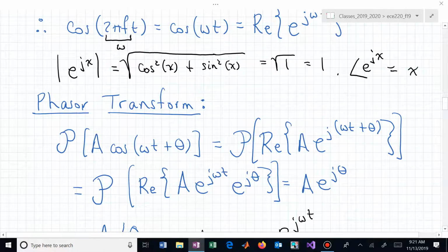All of that to help us get into the frequency domain to do phasor analysis. We want to now, instead of having to deal with sines and cosines, which get messy when you're adding, subtracting, dividing, multiplying, let's now play with complex numbers. Then it's cleaner, and we can go back and forth. Oh, you give me a time domain expression, I want to go into the phasor form of that, or into the frequency domain. I want to do my analysis in the frequency domain, and at the end I'll give you back your time domain answer when I get the analysis complete. What we do is we do this phasor transform.